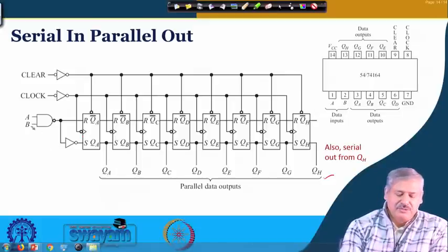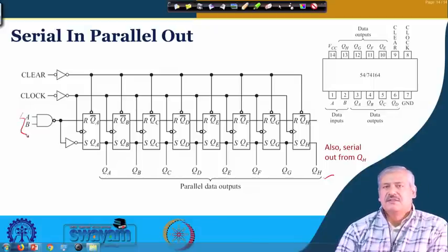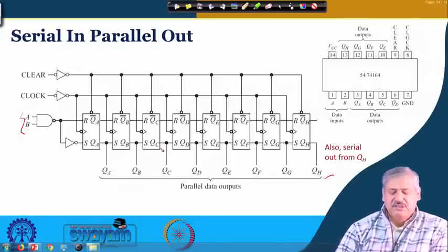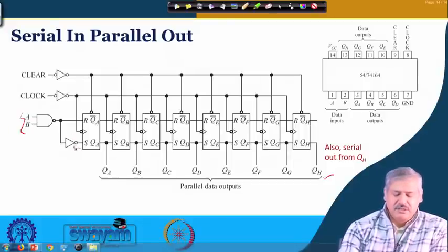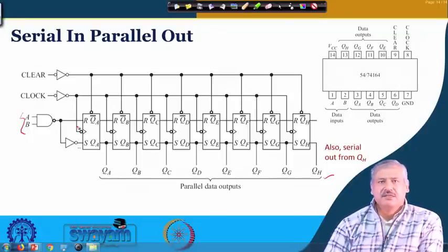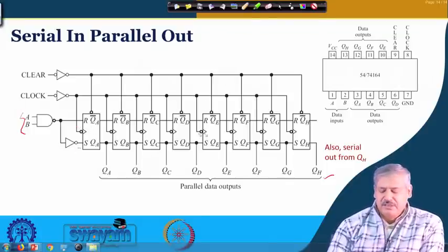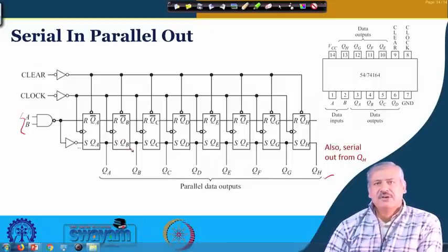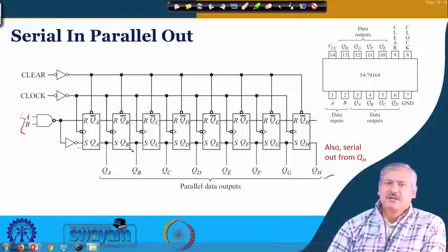You see that these are the two inputs. One of them you can consider as a control input, say B. When this is low, this particular input over here will always be low. So, the S input will always get low, and R is always the inverted version of S. That is the way we usually store the data. Effectively, this one is a D flip flop, the rest two of them are SR flip flops. We do not need an additional inverter to convert it to D, because we can connect directly internally and get the shift register action performed.